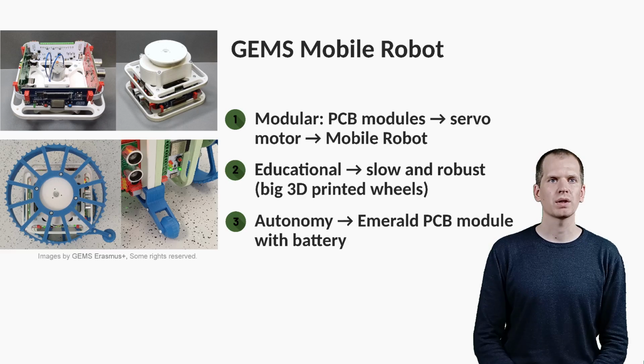The gearbox attaches to the base and has 5 compound gear pairs with reduction ratio of 3:1 on 2 steel axles. This gives us a high reduction ratio of 243:1. The output shaft rotates slowly and has a lot of available torque. For the torque to be transferred to the drive wheel, the output shaft is fitted with custom-built bearing. This again, decision based on educational value, being able to demonstrate the working of an important mechanical component.